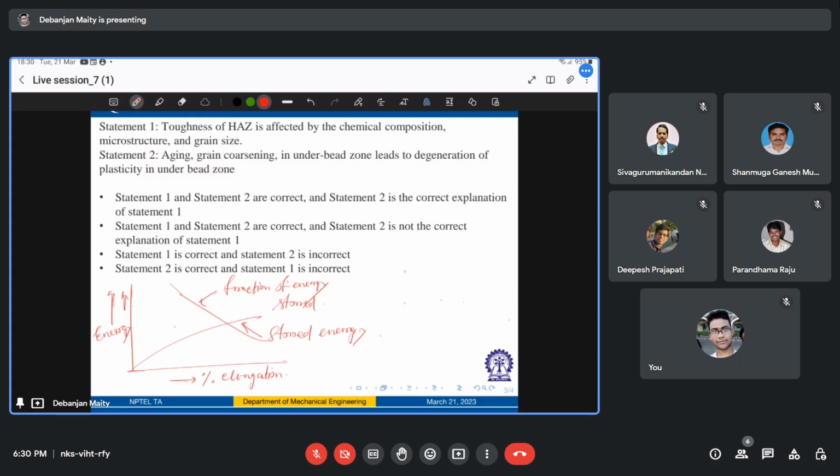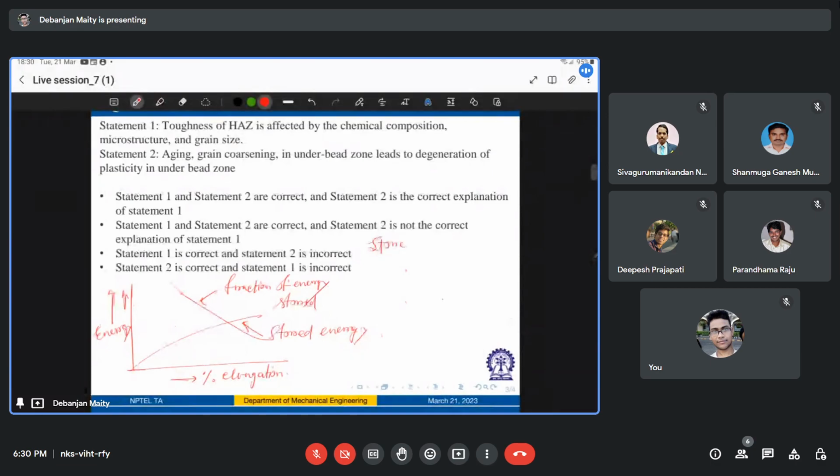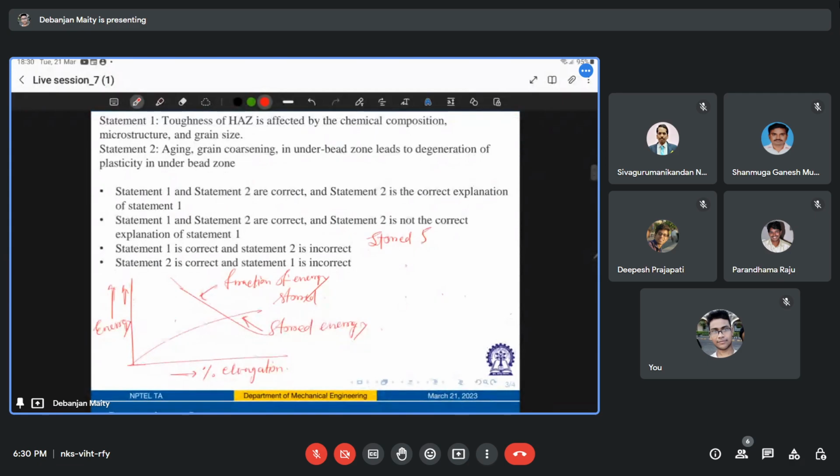Okay, so whenever a work hardened material is annealed, the deformed grains in the material tend to recrystallize by forming fresh and strain free grains that are soft, just like grains that have not been deformed, right? And the stored strain energy is the driving force for this recrystallization of this work hardened material. So you are having stored strain energy as the driving force.